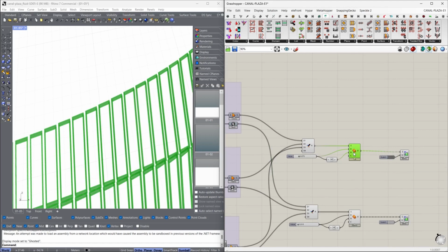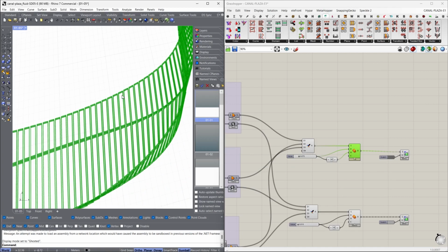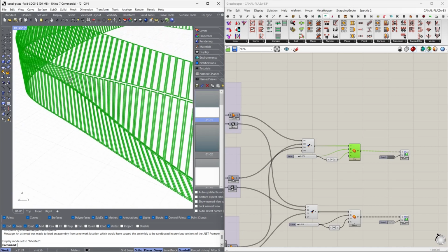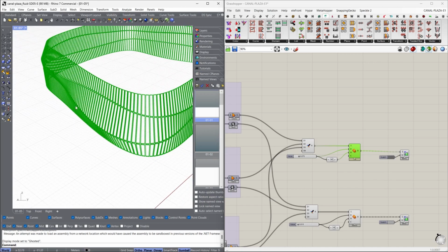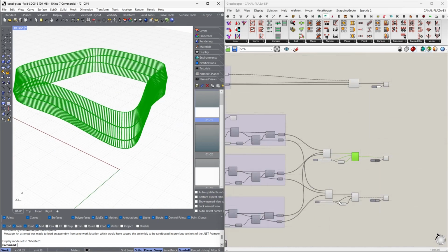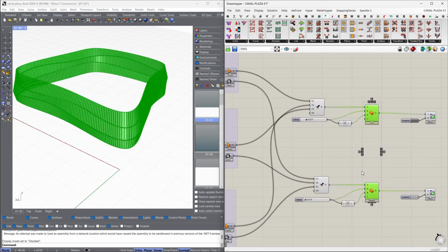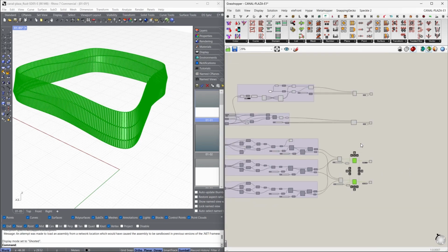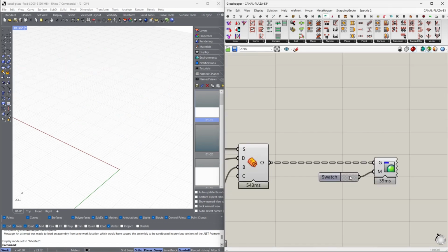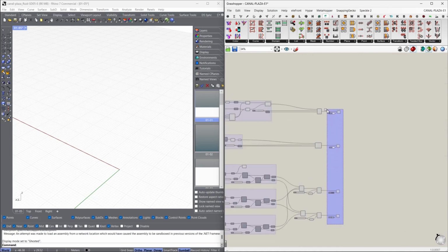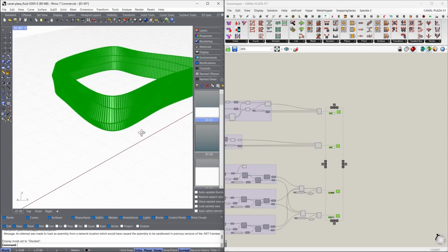The frames we also give thickness with the pufferfish component, and you can see all the different planar frames there, which the script generated, and then the same for the glazing, which comes in between. And that essentially gives us the whole thing. Then I just did a color preview for the glass with a bit of color, gave it some transparency. And then if you select all 4 of these, that's the full facade over here.